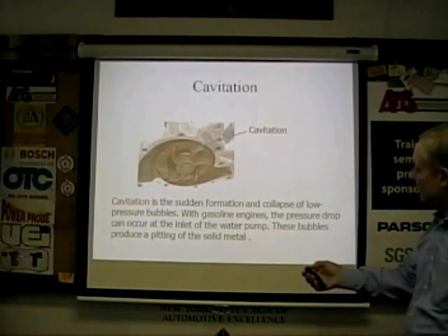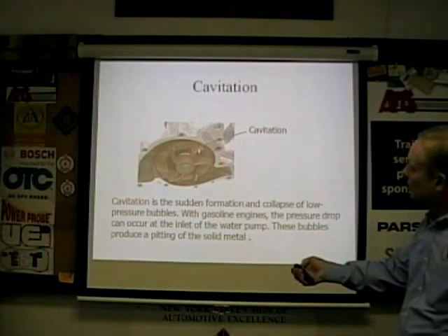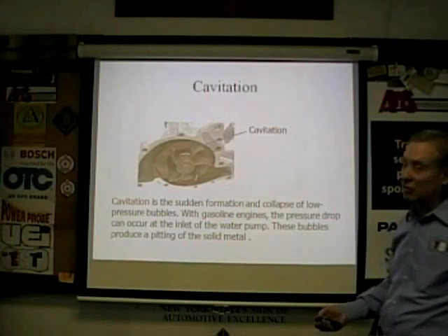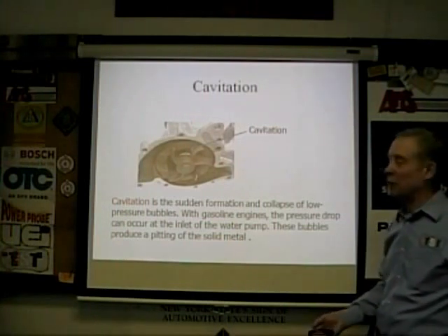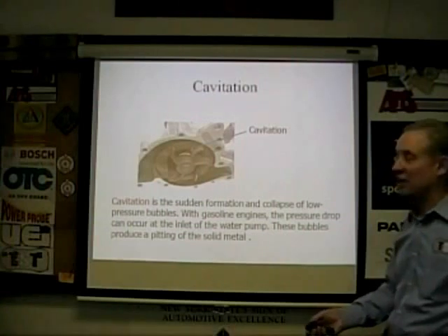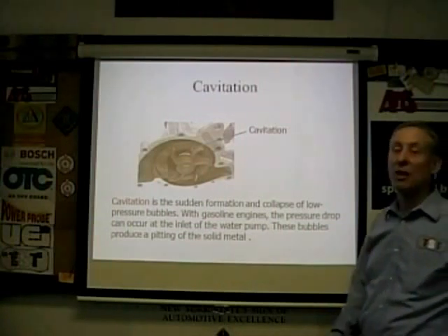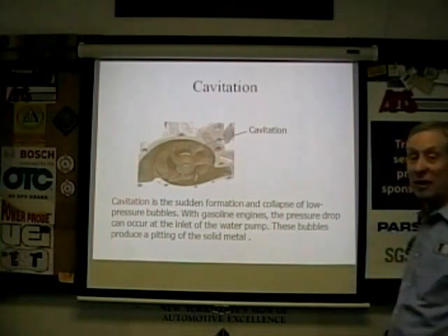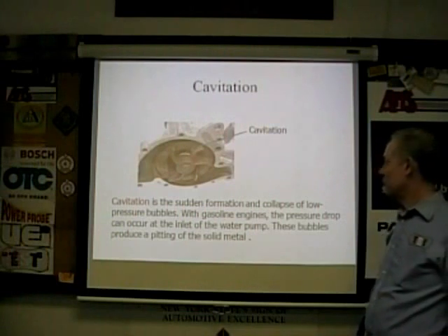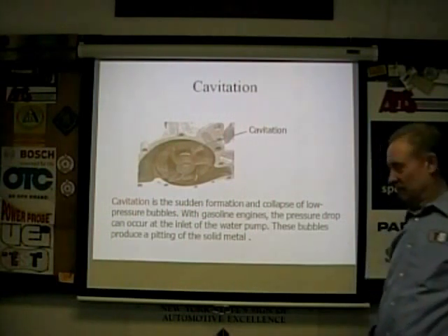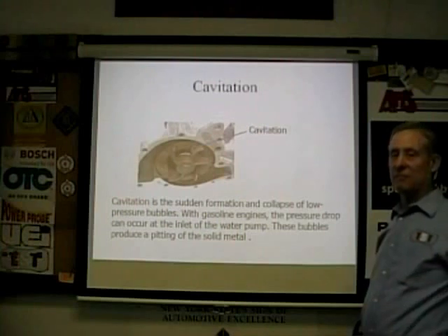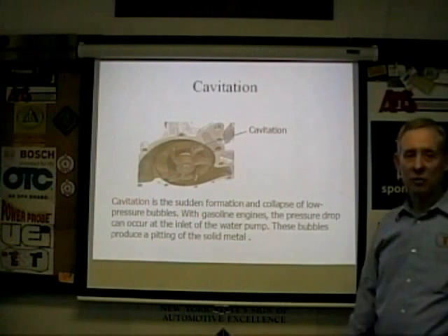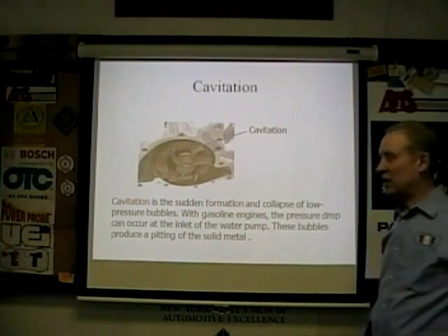There's an impeller with pitting, that's cavitation. The bottom line is there are pits in the impeller, and that happens because it's not just coolant makeup, it's pressure also, it's flow restrictions. You end up with such a big pressure change that there's air bubbles in there, and they literally explode on the surface. Exploding air bubbles cause damage. And by the way, sounds crazy, if you're using something like an airlift or a machine like a Flow Dynamics, whatever, that fills them up, takes the air out, and you keep getting bubbles, it's due to cavitation, you have a part that's been damaged due to people putting the wrong stuff in.